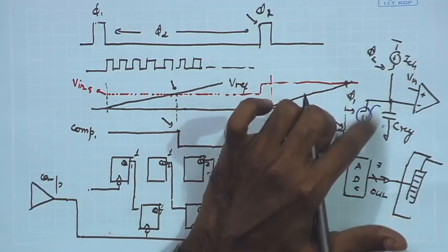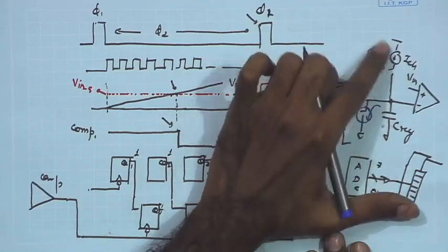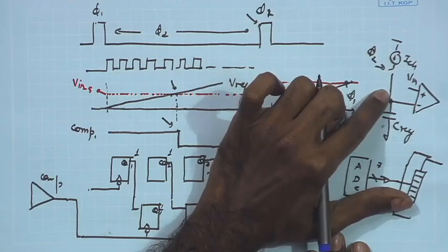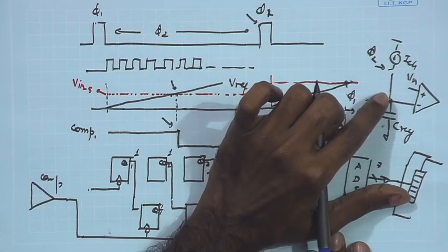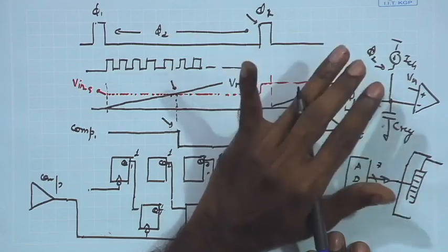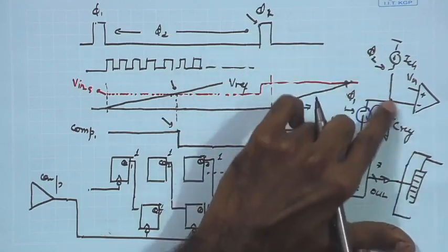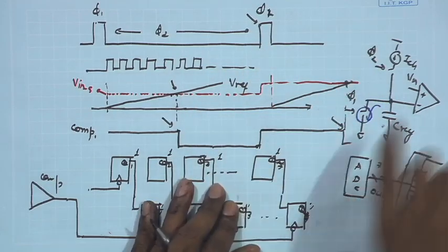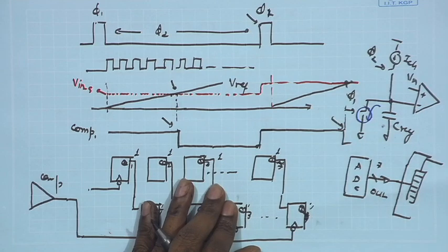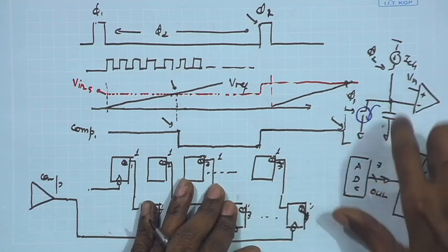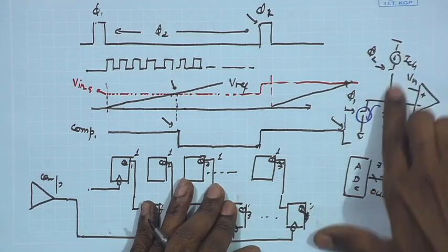That leakage component can be of the order of say few tenths of nanoampere. If I keep this leakage component sufficiently small as compared to the charging current, say at least 100 nanoampere, then still the slope may not change significantly. So there comes the trade off. You have to be careful while designing this charging circuitry that we need to make the slope constant, right, and in order to make the slope constant, we are using this constant current source.